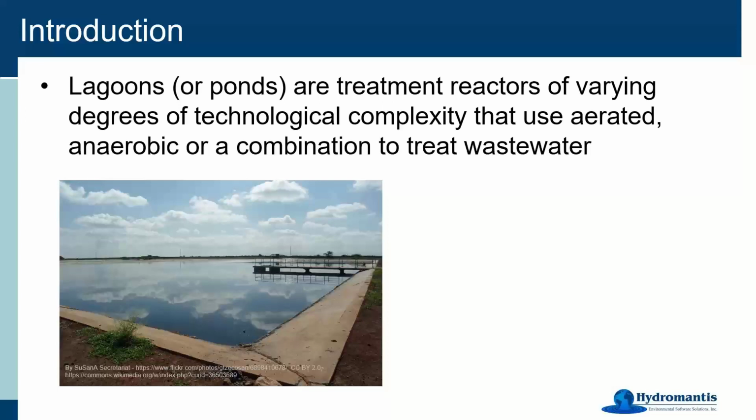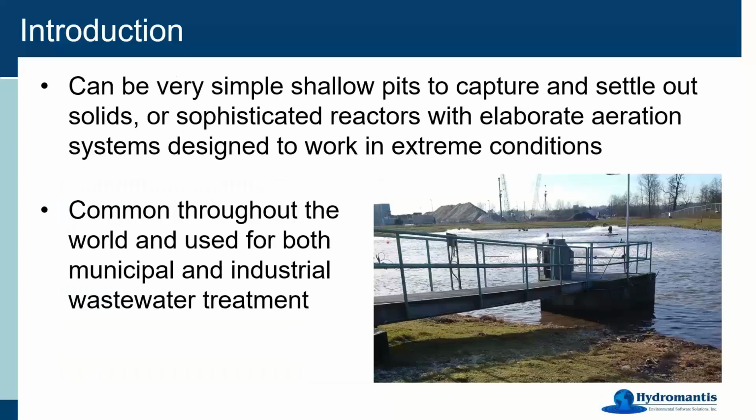So some of these systems can be just completely on their own. They're just a large anaerobic reactor and settler, or they can actually have fairly complex aeration systems and mixing systems and control of the flow in those things. So it becomes a little bit more complex problem when you want to try and model that sort of a system.